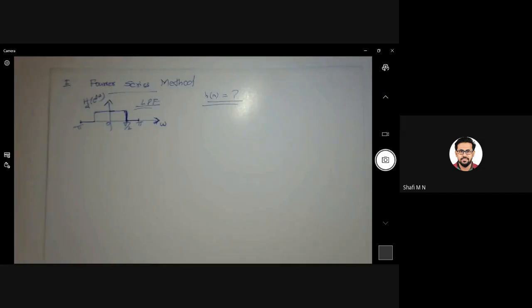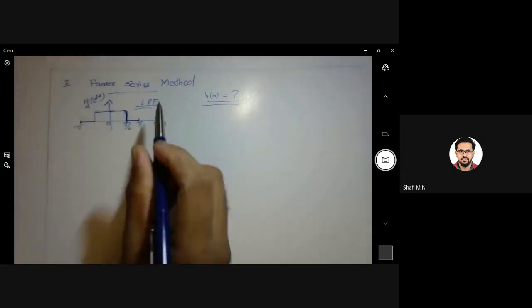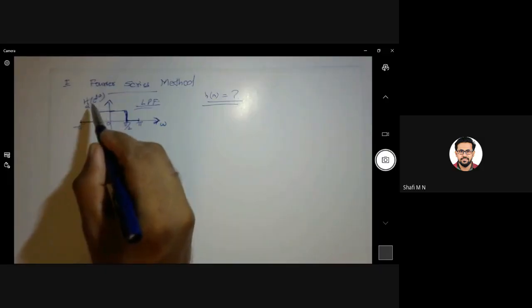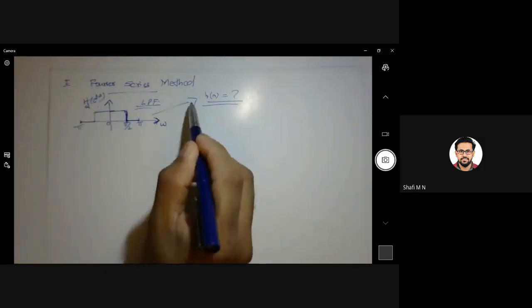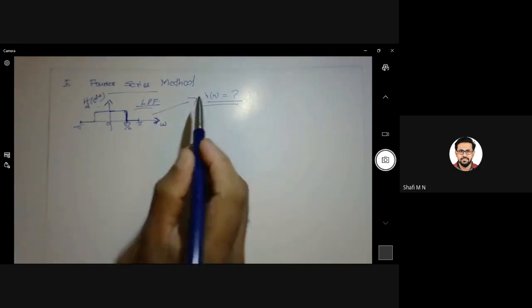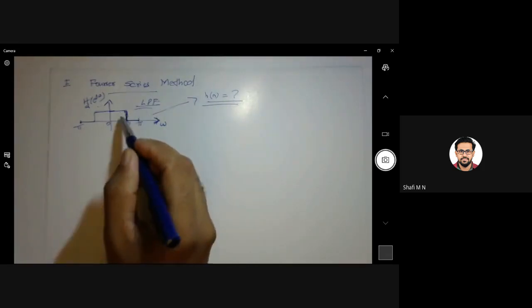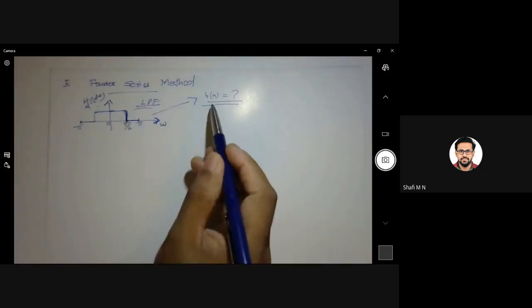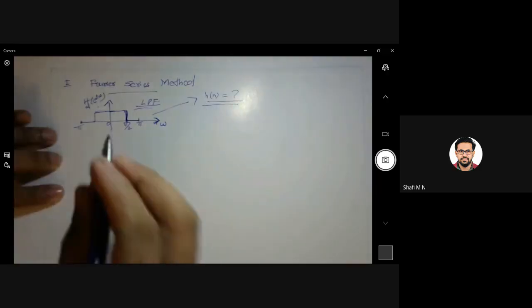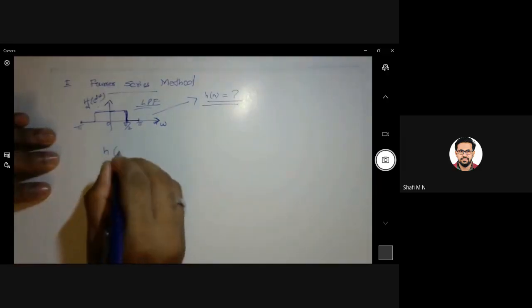Okay, so this is the desired response. HD, capital H, the frequency response, is available with me. I want the time domain. So what is the easiest method? You transform your frequency domain to time domain. You take the inverse Fourier series. That means you find h of n. Let me call it h of n.